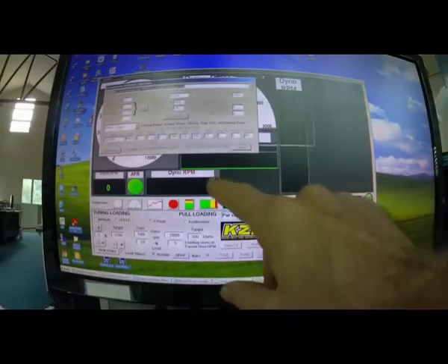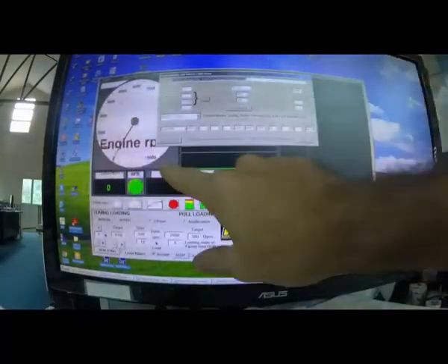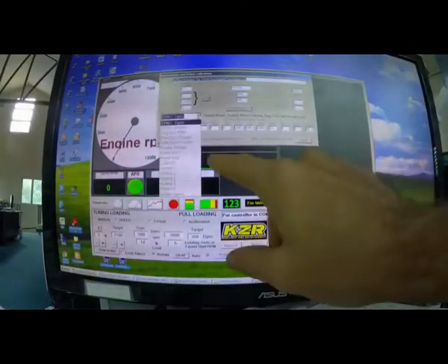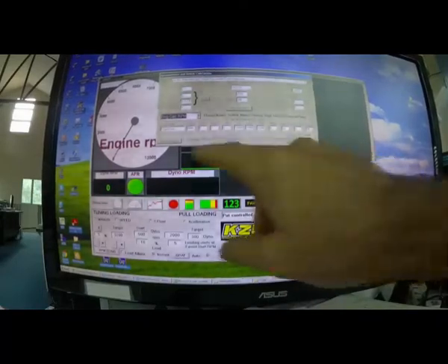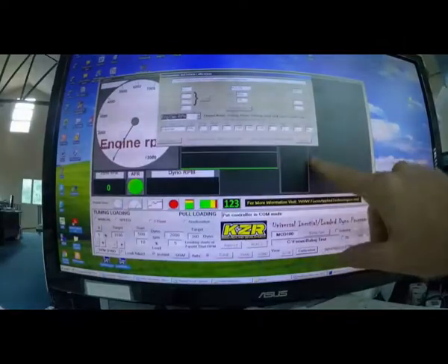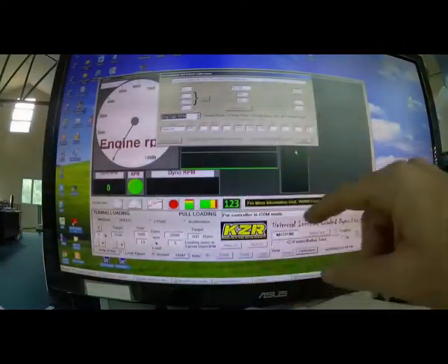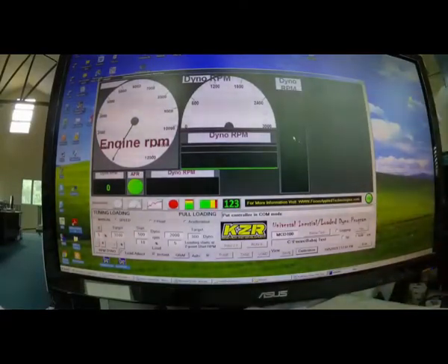So for example, you'll see we've got how many major ticks here. We've got 12 because it's 12,000 RPM. And so in that case, we're talking about the engine channel. So we've got 12 major ticks and 2 minor ticks, meaning that you've got 2 separate places between the major ticks in there. So you can set up all that in here. When you're happy with it, you say set. If you don't want to change anything, you say cancel. That's the basic calibrations.